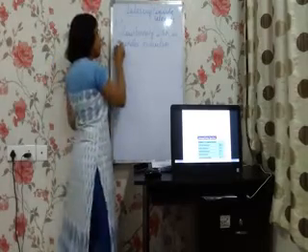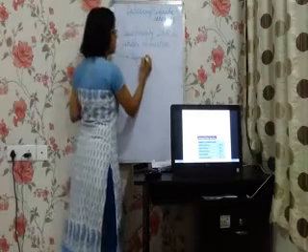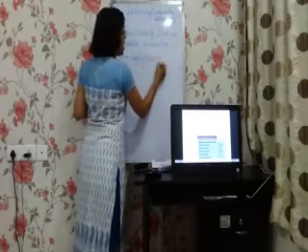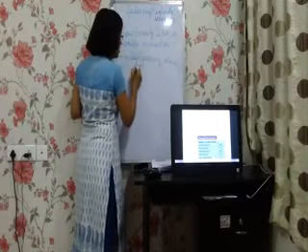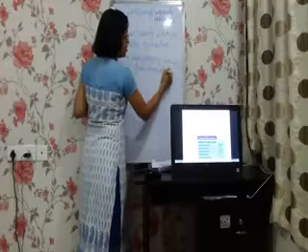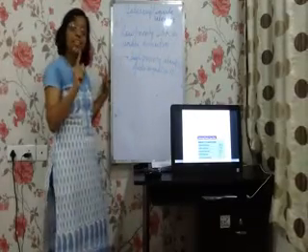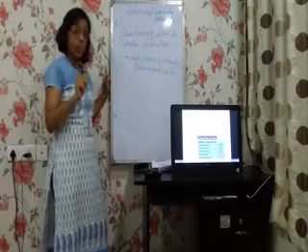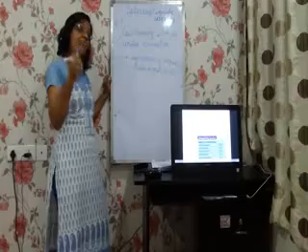In between, suppose a high priority interrupt gives a signal to the microcontroller. When this signal is received, the low priority interrupt ISR is not over yet, but still another device which is at a high priority has given a signal.